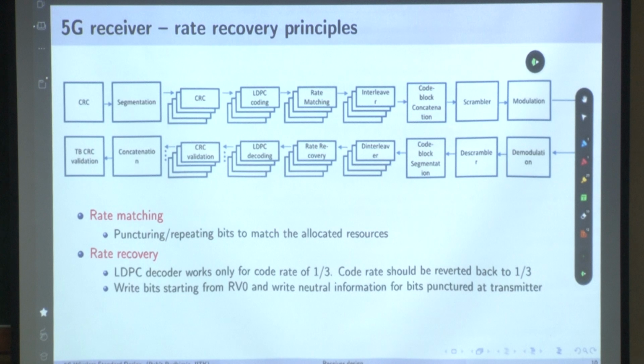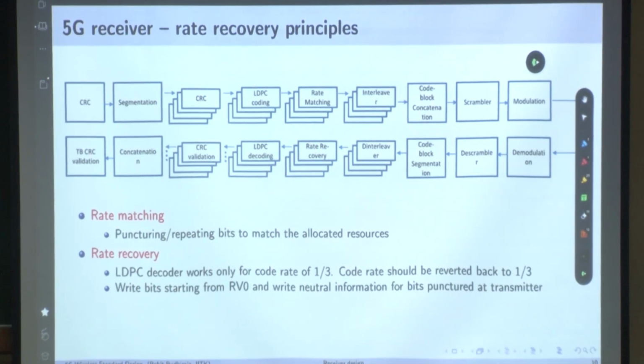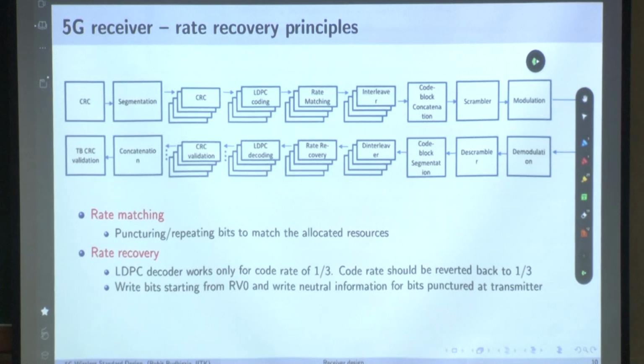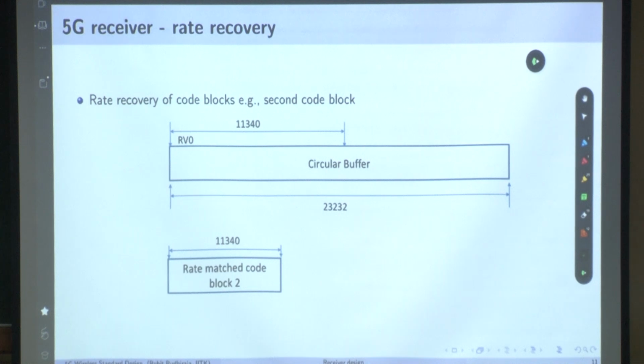Do we understand this? If it is redundancy version RV0, you need to implement this circular buffer at the receiver also. So if it is redundancy version 0, what will happen here? I'll draw this. How many bits did you transmit? This is n, the bottom is n. This is k. This is what you transmitted. You did not transmit this, because that's what was asked by the user.